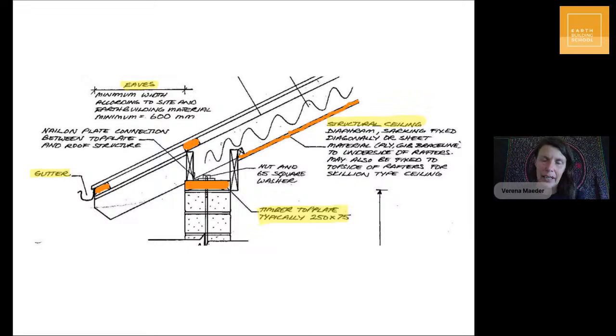They are additionally stiffened by what you call a structural ceiling diaphragm. So if you imagine the whole building as a box, like a shoebox without a lid on, you can imagine that if you start to push on the sides of the box, the top could go like this, because the bottom of the box is in the ground and often has a concrete pad, it's stiff, but the tops of the walls are not secured yet.